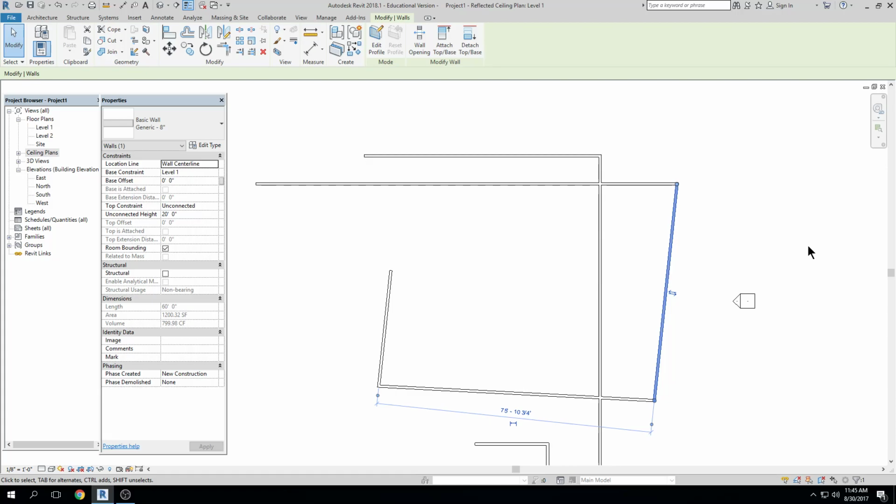In order for me to continue to select objects in Revit, I have to hold down the control button, click. Shift will allow me to remove, click. But what does Shift do if you hold down the middle roller button in AutoCAD? Pops you into 3D, right? So you get used to using the Shift button in Revit. When I tell everybody in AutoCAD, unless you're working in 3D, keep your hand off of the Shift button, because you might bump into 3D a tiny bit and then you draw crooked lines. They're not straight. So this is kind of my biggest pet peeve with AutoCAD and Revit.